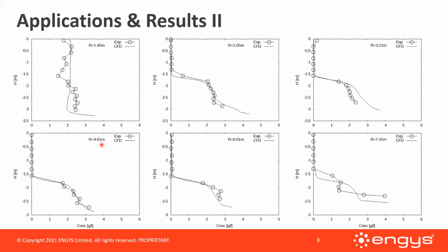As to be expected, in the first sector, which is located inside the well buffer, the comparison is not as good, because there the effects of the actual inlet shape on the flow are largest since it's close to the inlet. Overall, we can conclude that the employed method is suitable for CFD analysis of settling tanks. The employed method is both sufficiently accurate and numerically fast enough for this type of application.